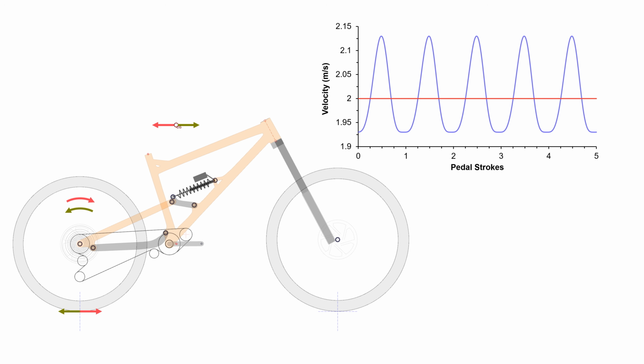As you recall, whenever the bike accelerates or brakes, the force is transmitted through the tire's contact patch. That ground force is acting at the tire, while your drivetrain or brakes are applying a torque at the hub. These two act at different points, and they create a net moment on the suspension, which is what causes anti-rise and anti-squat.